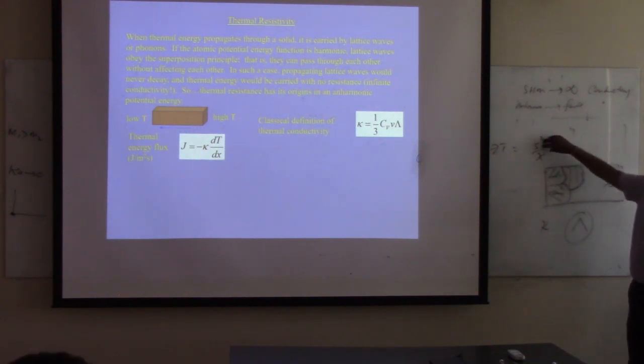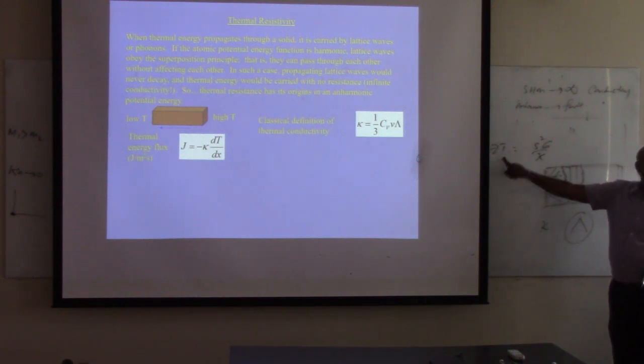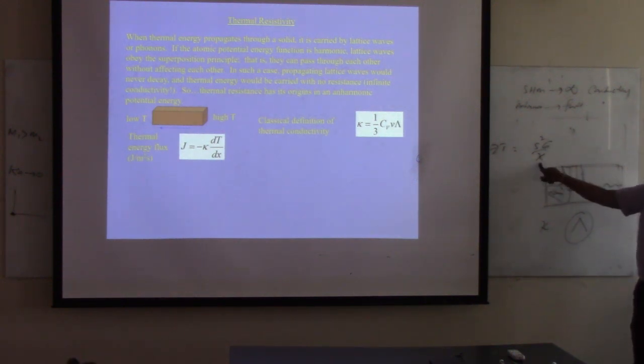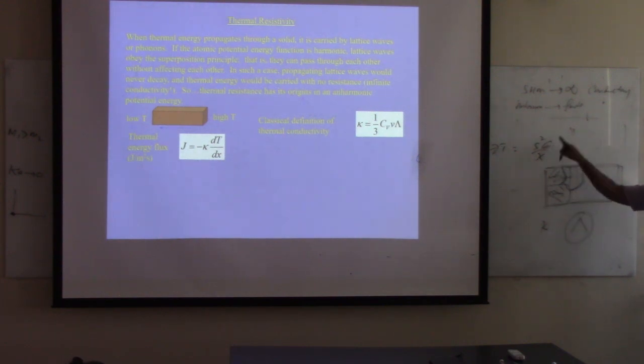Next chapter we are going to talk about electrical conductivity. So far we have been talking about thermal conductivity. If you want to get higher figure of merit, you need to have very small thermal conductivity. But still you need to maintain higher electrical conductivity. So this is a very tricky problem. There are a lot of ways people try to address that. So your electrons can pass through some areas, but phonons can get scattered. That means sigma is still not affected, K can be reduced. So that's a very important thing.